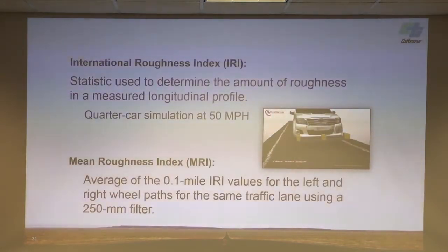Okay, the International Roughness Index. So this is a worldwide standard that I think most states have adopted now, like 40 or 50 states. It's a quarter car simulation. So essentially, this inertial profiler goes out and measures the road profile, the wheel tracks. All that profiler does is give us the elevations of the road every inch.